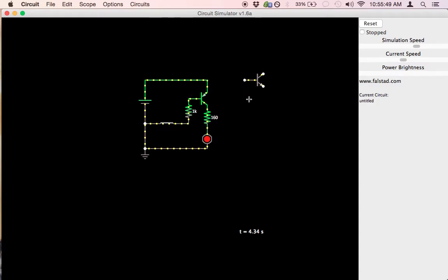How can we use transistors to invert a signal? What that means is in a logic circuit, a positive voltage is usually considered a logic high or a logic 1. It's a signal that represents perhaps turning something on, whereas negative voltage or 0 volts represents a logical 0 or what's called logic low, which may represent turning something off. And we're going to see how a transistor can easily convert a logic high signal into a logic low signal or vice versa.